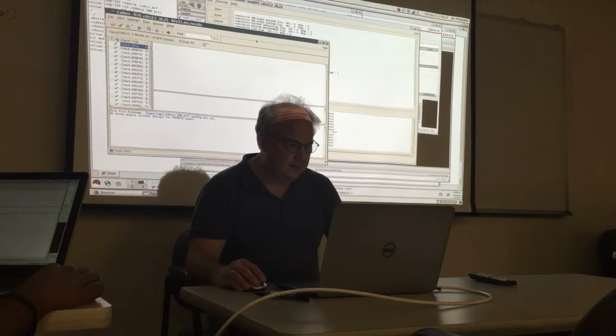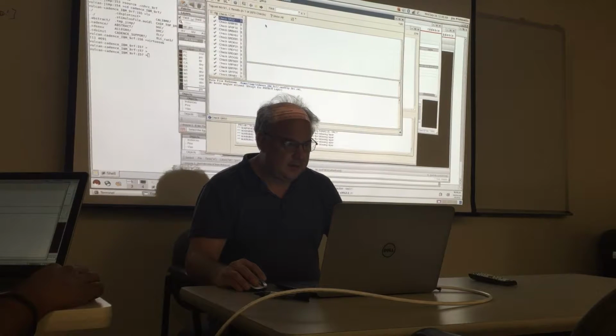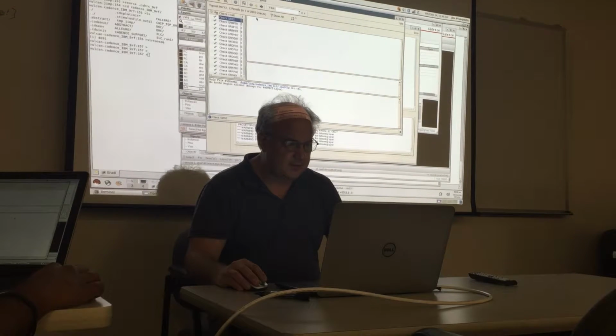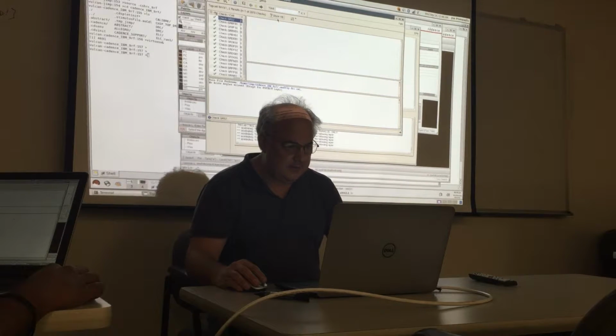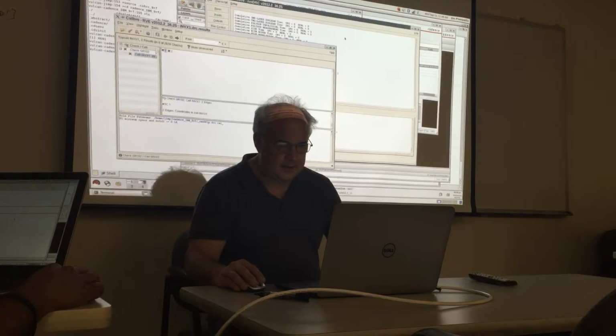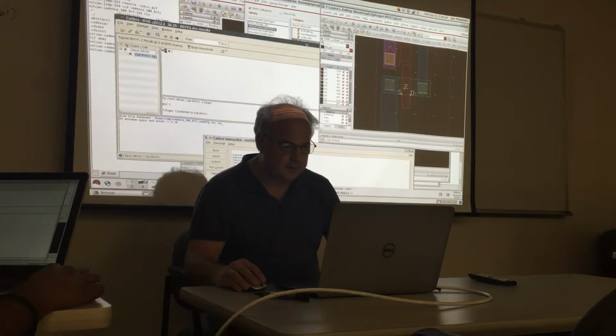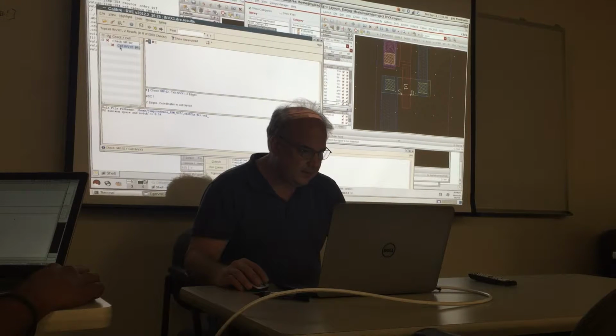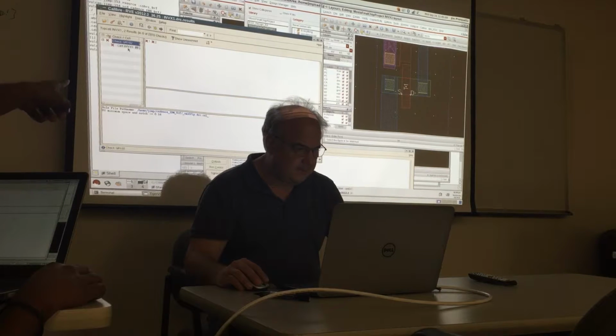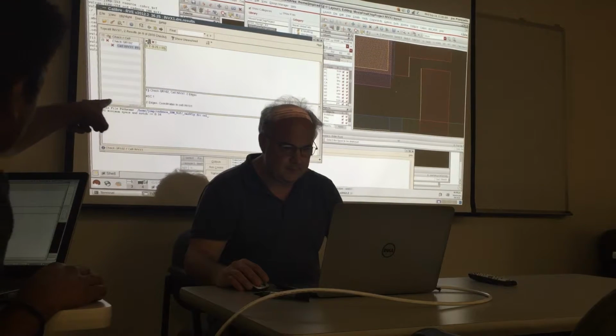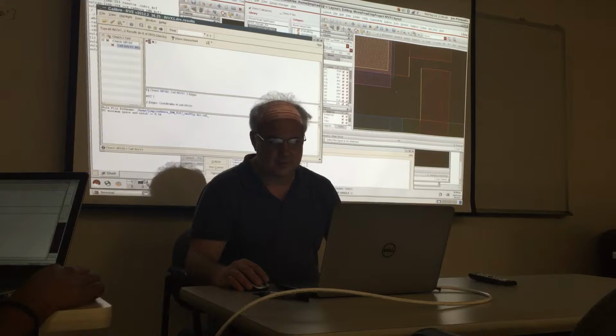Okay, and now I got one. And you know, I usually put a frowny face on there. I think the LVS does the frowny face, but then you can go here, show unresolved, and then if you click on it, let's see. We have to click on the GR and then it'll show the option to highlight. You need to bring the window up so you can see what's going on. When you click on that one, and then at the bottom, you double click it, and it goes right to where the violation is.